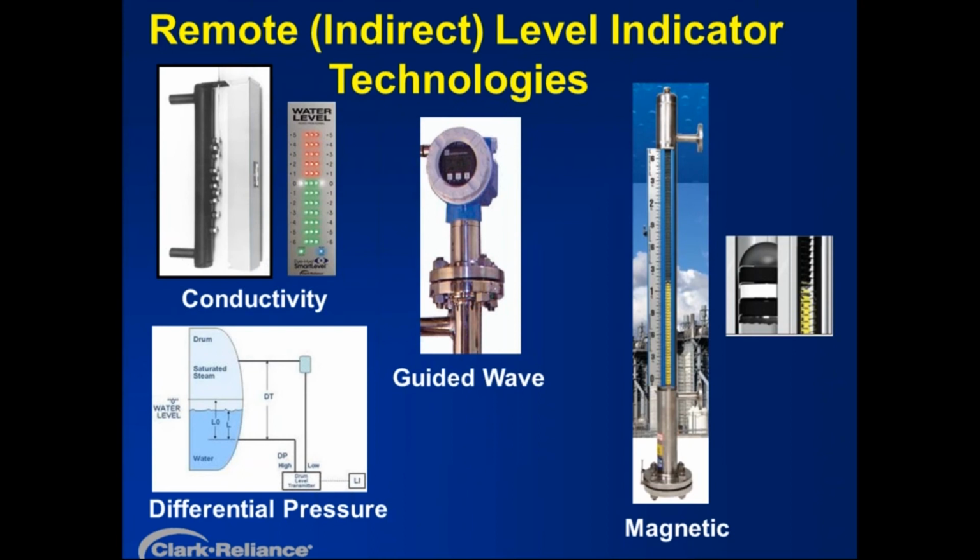However, when used on a boiler, it's important that the boiler have high quality water with minimal particulate in it, because the way that device works, there's a stainless steel float in the center of that stainless steel chamber, and that float contains a magnet.